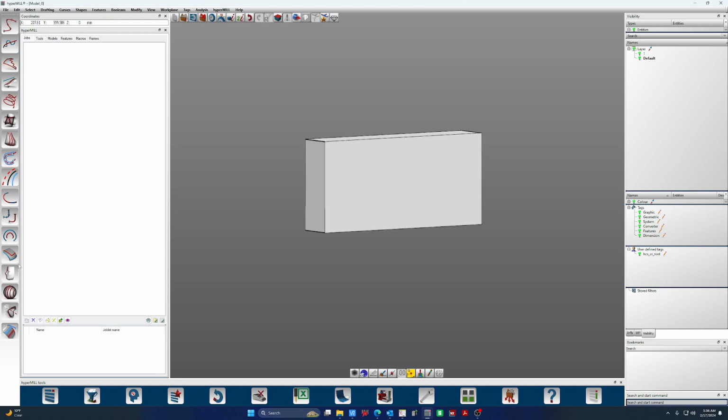Another thing we're going to do is the average curve is pretty commonly used, offset's pretty commonly used, and the projection function is pretty commonly used. Isoparametric is going to have its uses, some text projection. If you need to drive lines through center of cylinders, some of this other stuff, there's cleaner ways to do it. Joining curves can be convenient if you're not using the chain command, I suppose, or if you're ending up with just a ton of curves that are tons of little tiny segments.